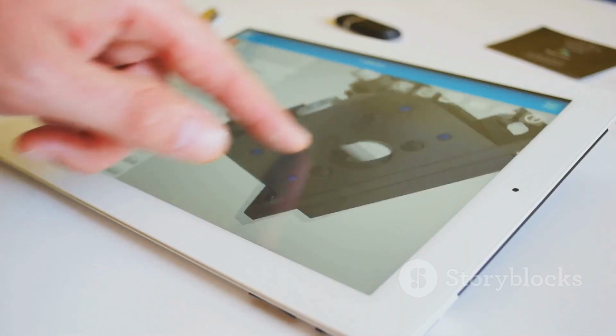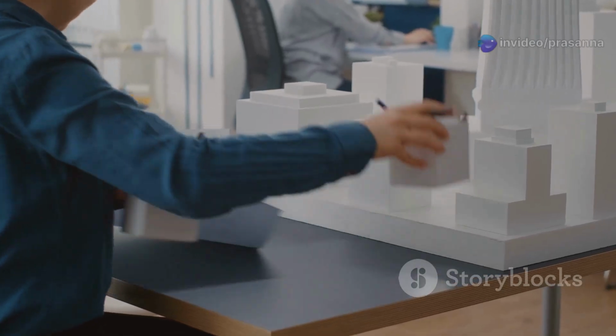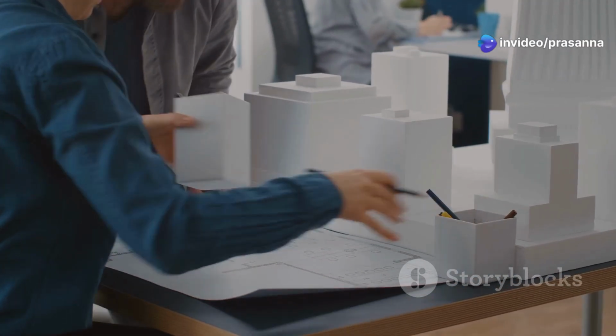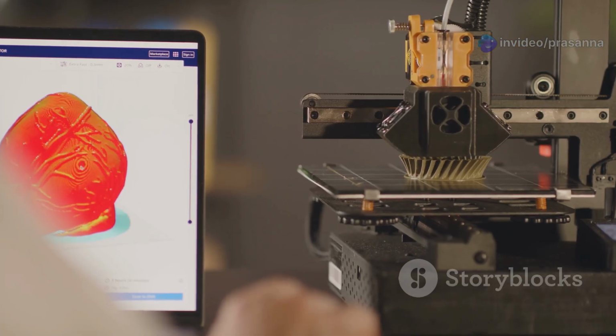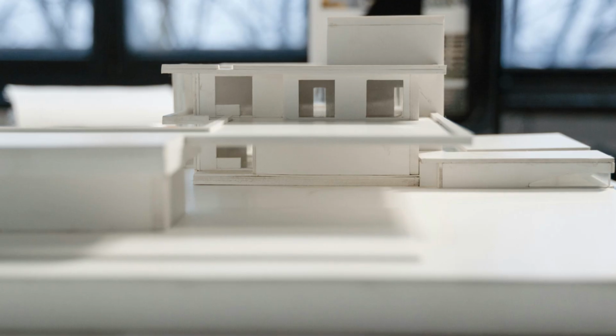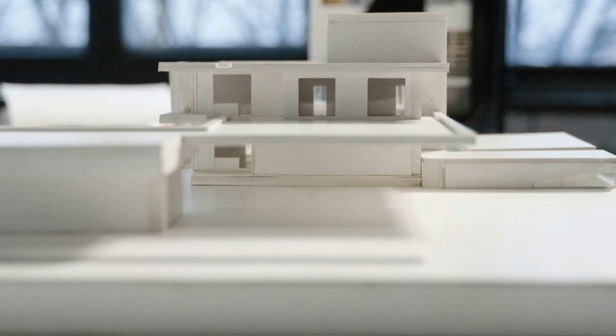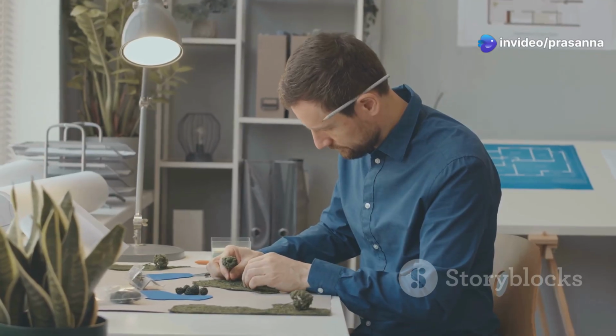One of the most important practices is using groups and components. When you create an object like a wall or a window, make it a group or a component. To make a group, select all parts of the object, right-click and choose Make Group. This keeps the object's geometry separate from other parts of your model. It prevents lines and faces from sticking together unexpectedly.